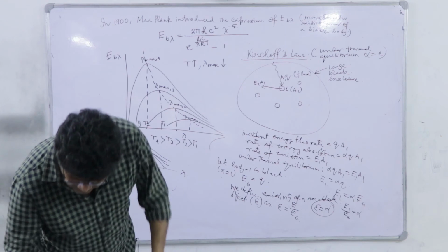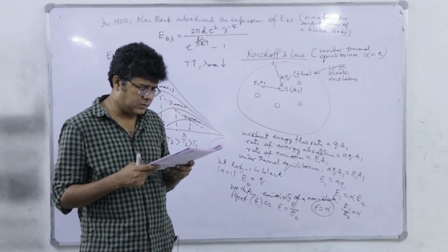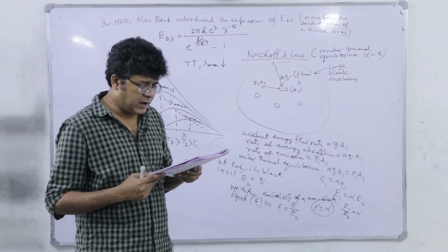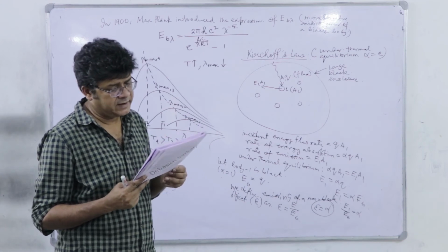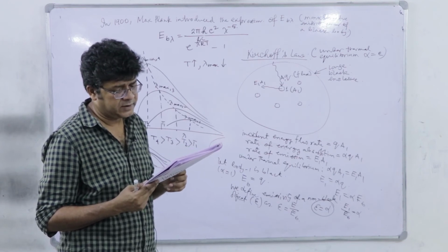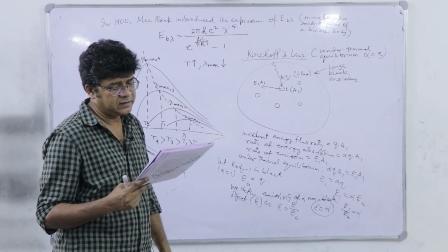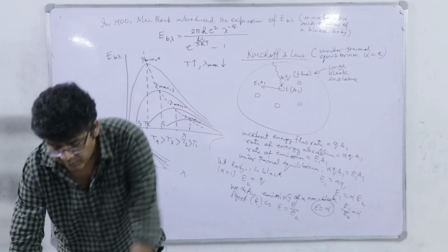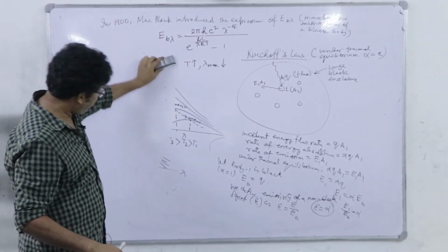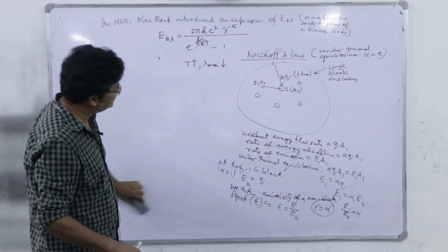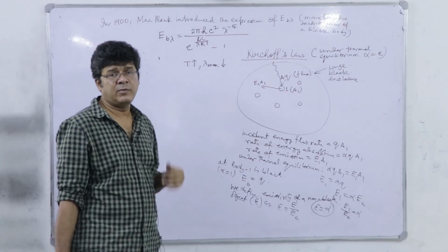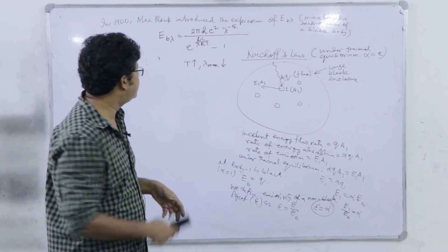So, you see, I have mentioned in the handout that the absorptivity of most real surfaces is relatively insensitive to temperature and wavelength. So, for practical purposes, it is customary to assume that emissivity and absorptivity of a surface are equal even when it is not in thermal equilibrium with the surroundings. But if it is necessary for a rough or approximate theoretical estimate, we can use Kirchhoff's law even when the body is passing through some radiative transients.